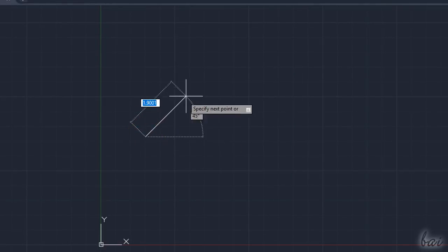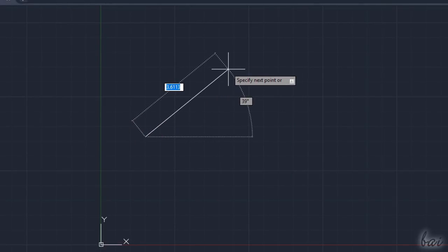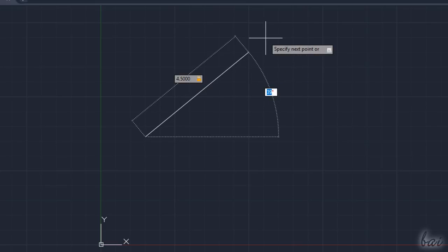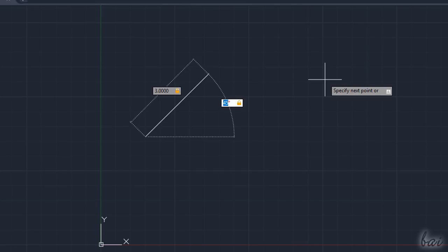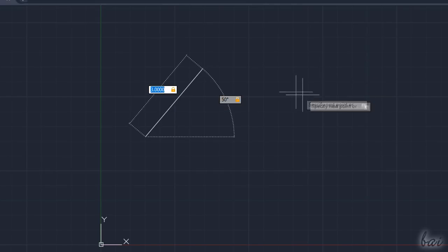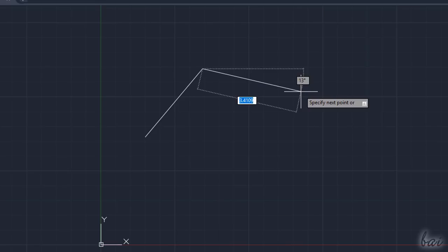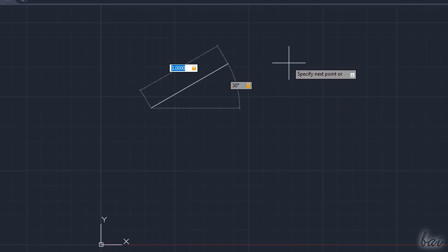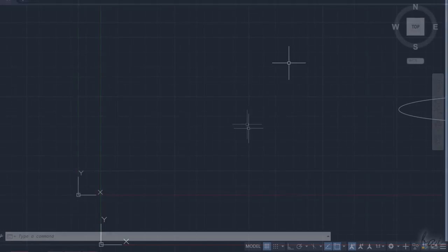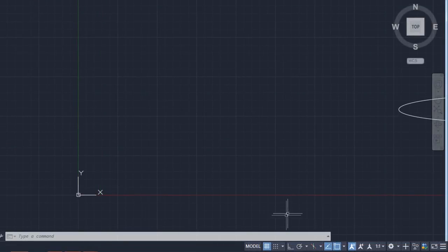With the object in progress, you can also define and set precise values on it by using your keyboard instead of your cursor. In this case, you can use the Tab key to go for the next or the previous property while checking the Preview in Progress and then apply the result with the Enter key or undo all with the Escape key. To help you realize drawings fast and precisely, AutoCAD has several drawing aids available, all collected in the bottom right corner of the workspace.